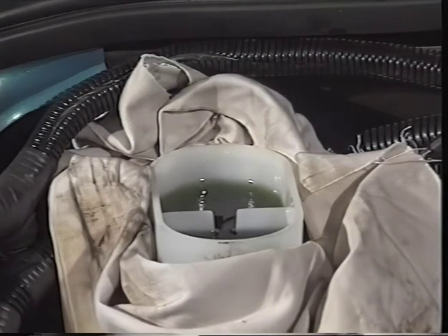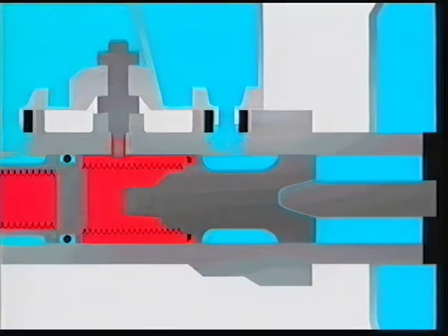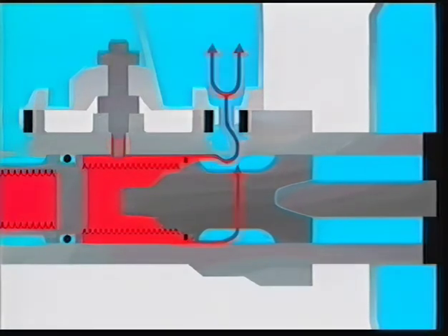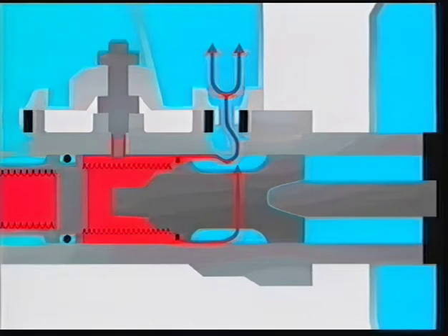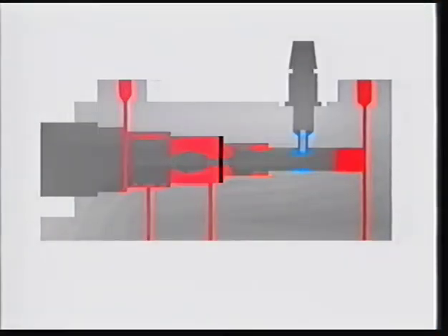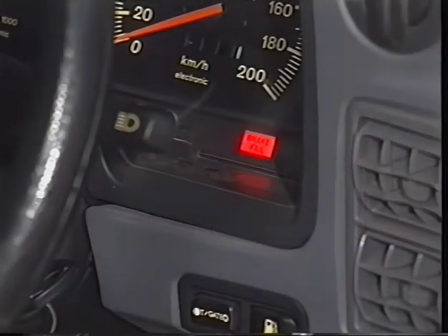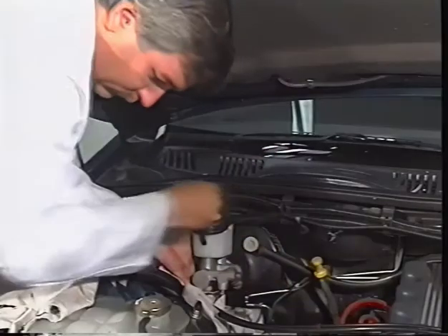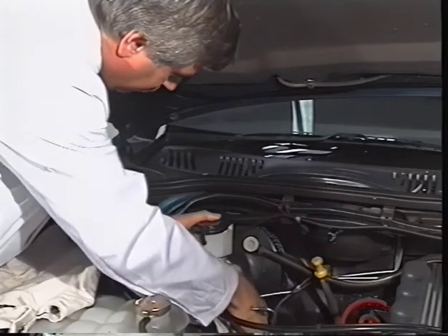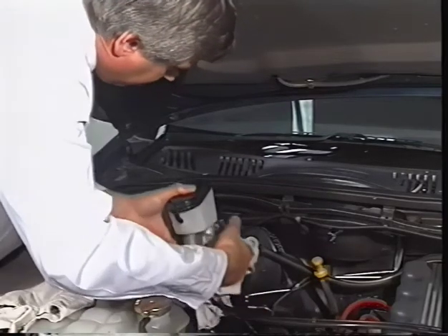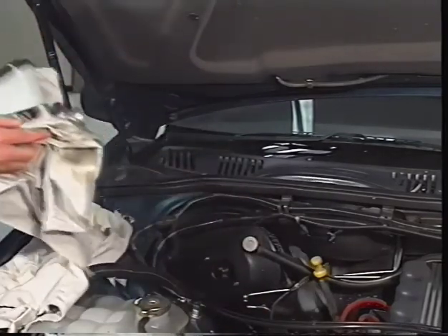On either conventional straight bore or fast fill master cylinders, fluid may leak internally between circuits or over primary cups. In most cases, the pressure differential warning switch should sense the difference in pressure between the circuits and illuminate the brake warning light. Both of the problems mentioned will require overhaul or replacement of the defective cylinder.